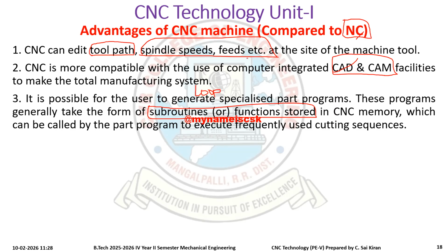But if you are using a CNC machine, suppose we are making a drill of 100 mm. Directly we cannot take a 100 mm drill bit and make the hole. So first we have to go with a smaller diameter, like 20 mm, next 50 mm, next 75 mm, and next 100 mm.